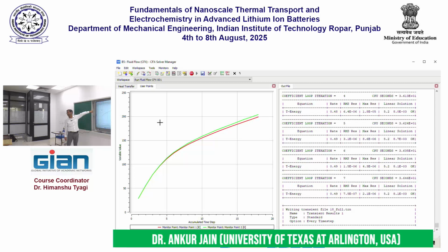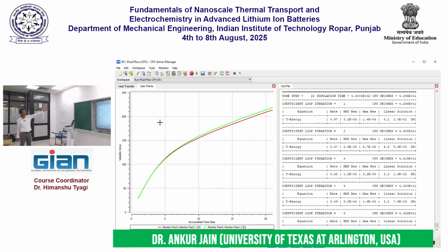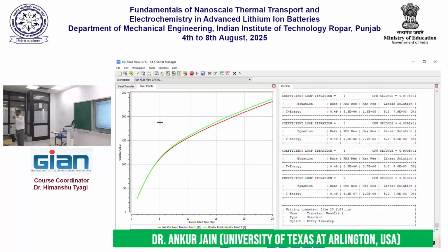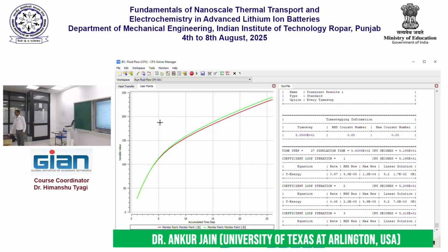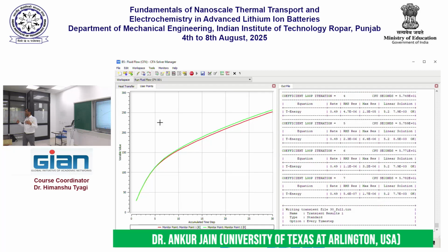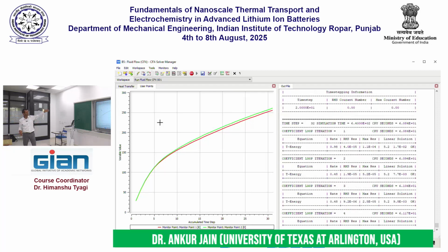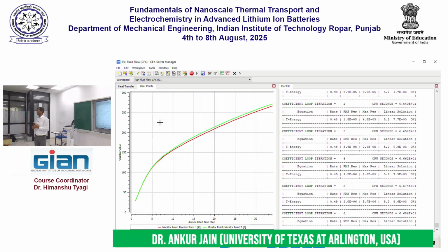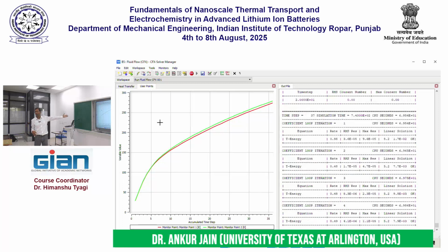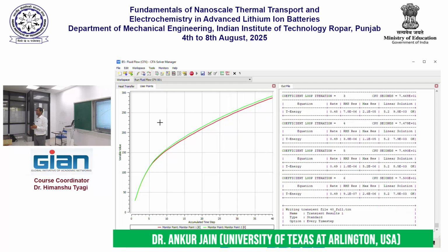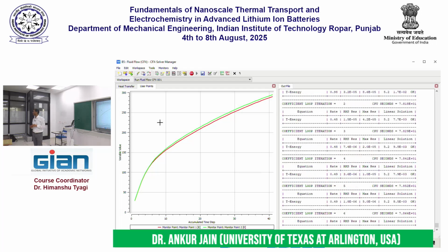The temperature rises very high, right? The cell will not survive. 50 watts was too much of heat, I think. At this point, 200 degrees C temperature rise, the cell will blow up. So we already know, if somebody says, I want a cell that produces 50 watts of heating, not gonna work. Not possible. You probably have to increase the value of H, cool it more aggressively in order to bring down the temperature, right? Using this simulation framework, you can ask all these questions. What is the minimum H needed to be able to accommodate a 50 watt cell? Can I switch off one of the cells and only run one of them at a time? Will that help me reduce the temperature and so on?